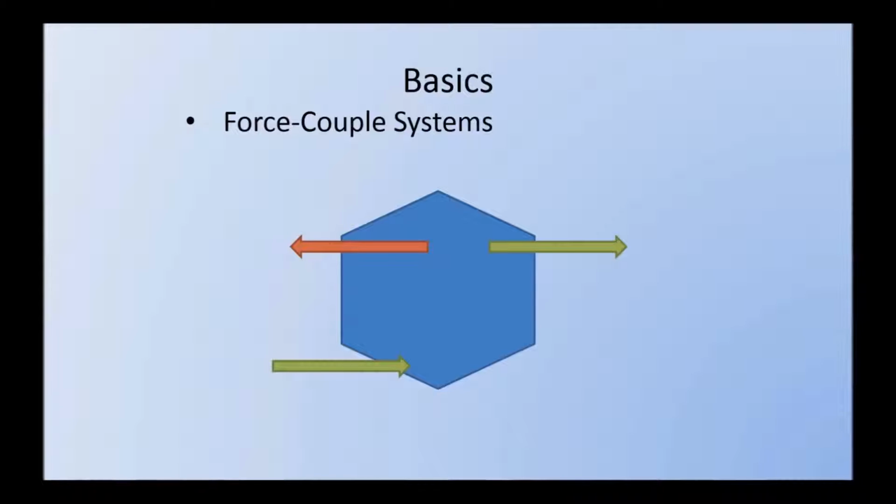Now this is done by the placement of the red arrow, which is at the same perpendicular distance, d, as the green arrow. Now, because of this, it has the same moment arm, and therefore creates the same moment, but in the opposite direction. So this is shown by the orange couple you see here. Now, both the forces and moments are balanced, and we are done.